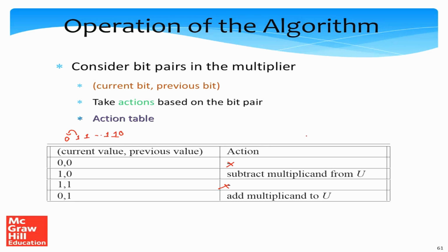Look, in a multiplier, if we have zeros, we don't do anything. So that's the best thing for us, that if a number is zero, it essentially saves us effort. But if a number is 1 in the iterative multiplier, we are either doing an addition or a subtraction, which used to take effort, it used to take log n time. So since this was taking effort, we said what happens if we have several consecutive ones. So let's say we have k consecutive ones separated by zeros.